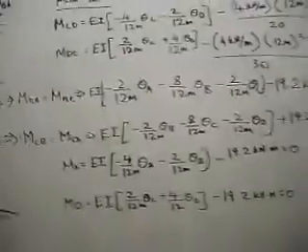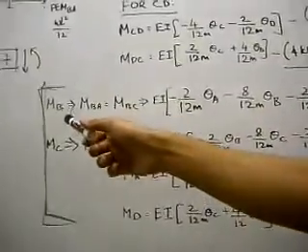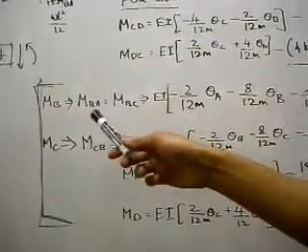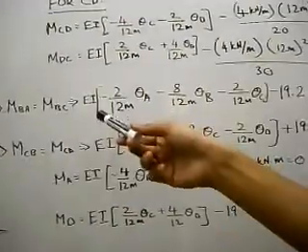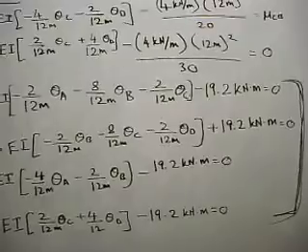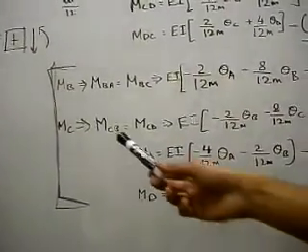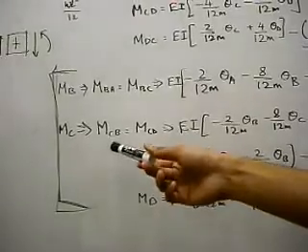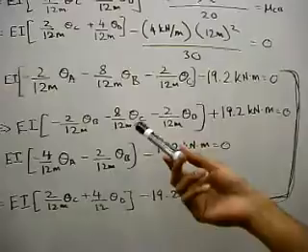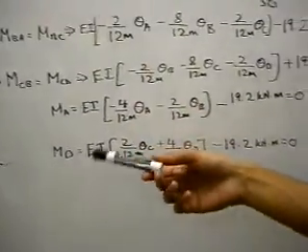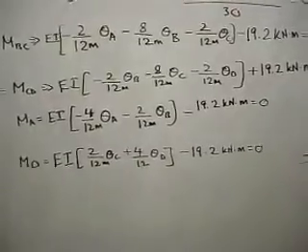And then finally, to get moments at B, we equated moment MBA and moment MBC and ended up with this equation. Of course, we assumed EI is constant. Did the same for moment C, where MCB is equal to MCD, and we get equations for M, theta B, theta C, theta D. MA and MD are going to remain the same because we had them equal to 0.